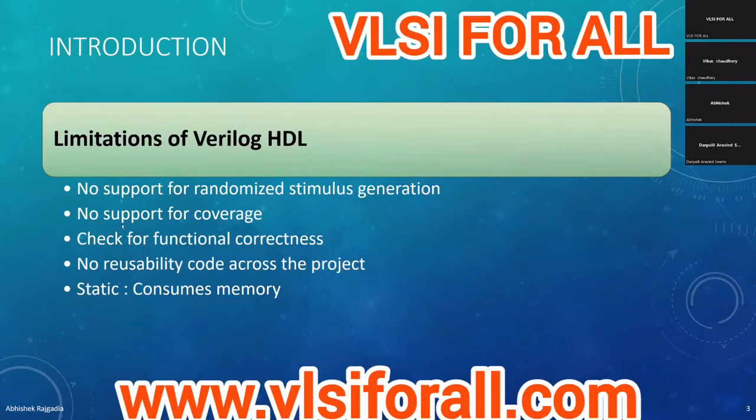Then the coverage. For the example of the adder, there were 4 scenarios. We'll write 4 test cases, or even write 1 test and cover all 4 scenarios. But what about designs which have billions of combinations of inputs? You cannot cover all of them. So there should be some metric which will tell you that the verification is good enough.